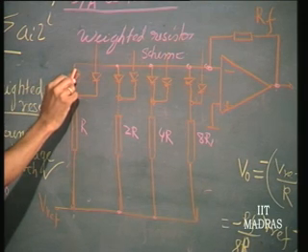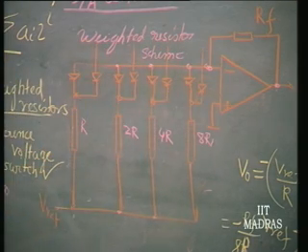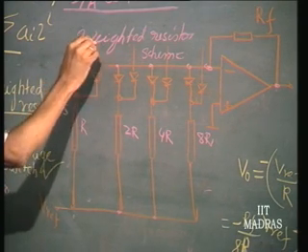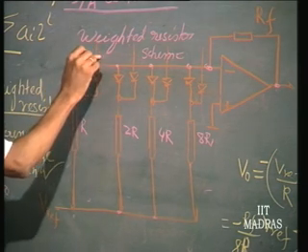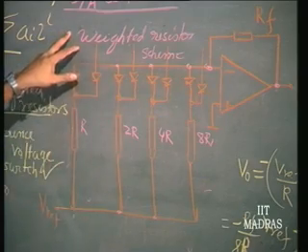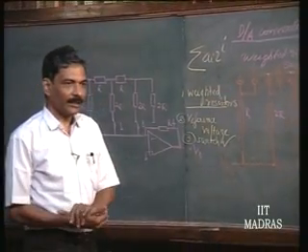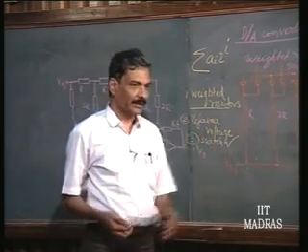Okay. So, these could be your digital outputs themselves directly, right. In the sense, you can therefore, I mean, actually use the inverted part of the digital. If you want the current to exist, this will have to be low, okay, then it will exist, right. So, if your actual input is 1 0 1 1, say, then what you have to apply to this will be 0 1 0 0, right. So, inverted. So, this kind of switch can work very well as the switch for this weighted resistor scheme.